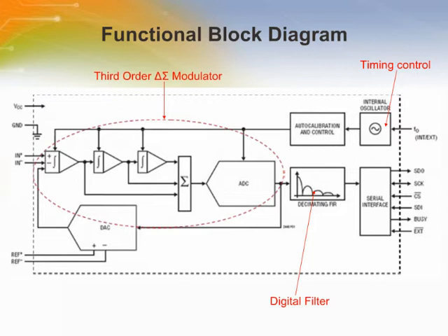The serial data input pin is used to select the speed resolution of the converter. During the data output period, the serial data output pin is used as a serial data output. During the conversion and sleep periods, this pin is used as a conversion status output.